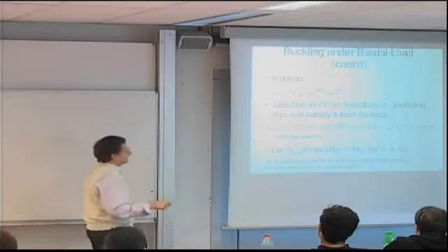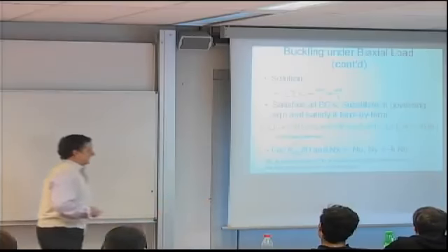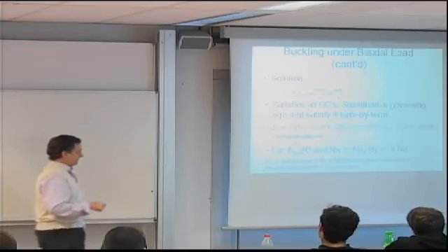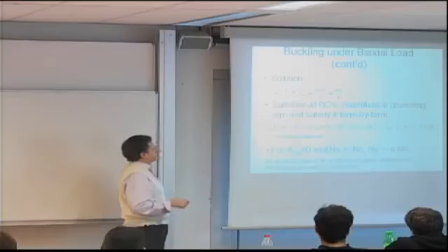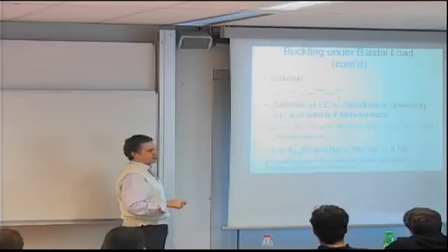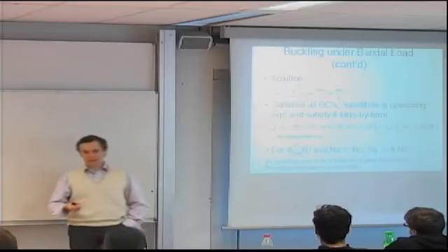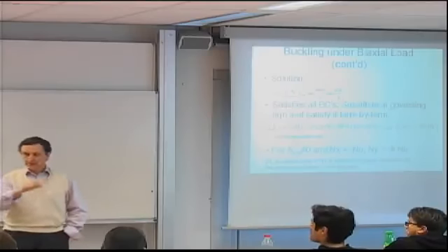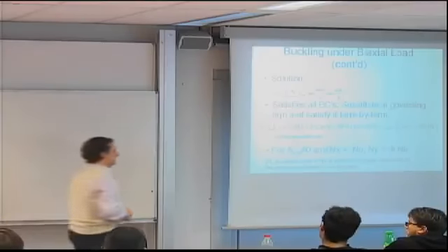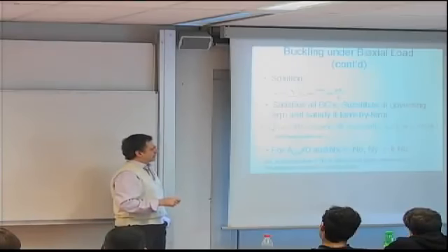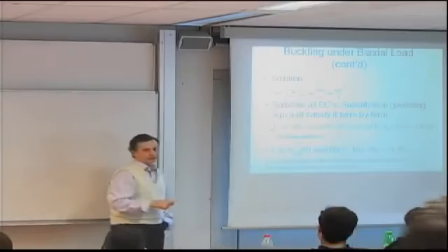Notice the loads are Nx and Ny on the right-hand side. And for convenience we define AR, the aspect ratio, length a divided by b. We also define Nx equals minus N0. That means if I find N0 in the end to be positive, I have compressive load. So it's just a matter of convenience to not keep carrying a minus sign all the time. And I also define Ny to be a certain multiplier k times Nx. So k times Nx would be minus k times N0.